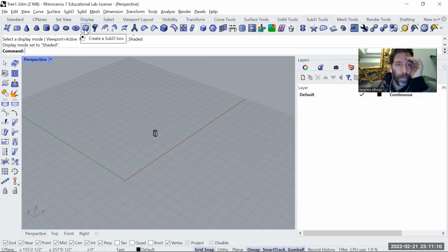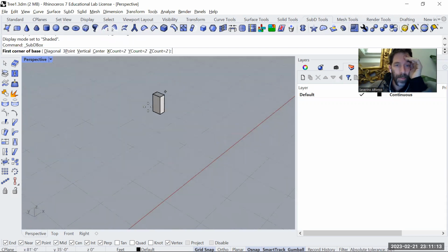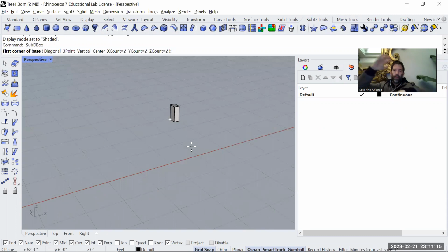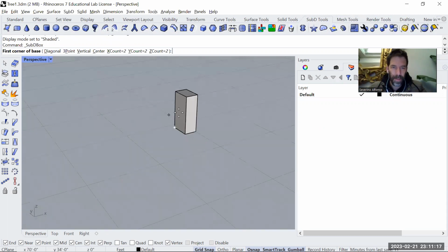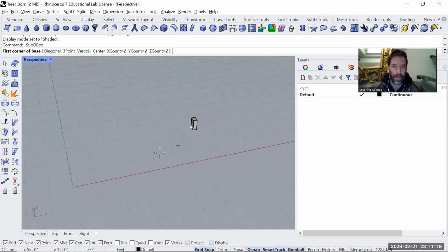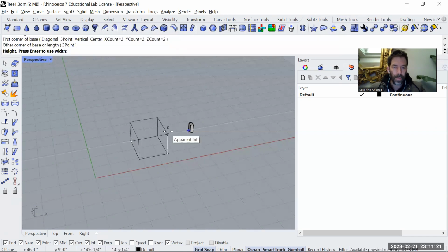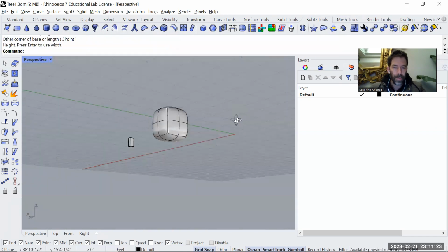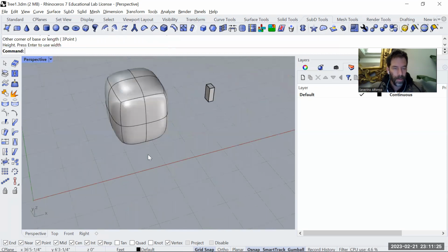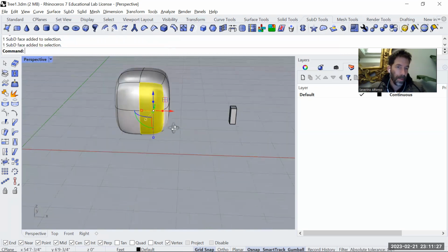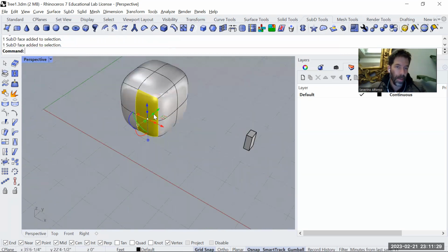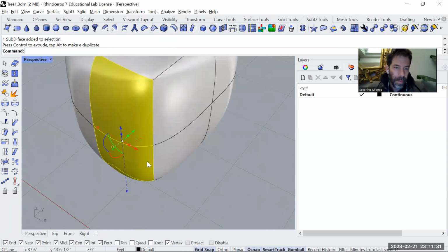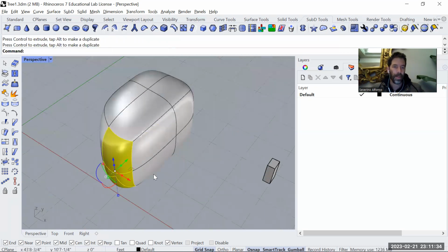One of the best ways to start is a SubD box, probably when you have the reference of your walls and your floors. I have a height of 6 feet there, like a person. So you can create a wall, one of these boxes, and then Control Shift to select faces. You can select one or another one. If you move those faces, it deforms it.